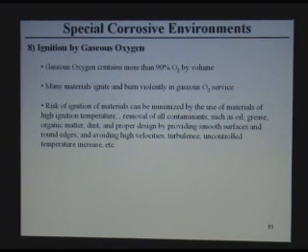Gaseous oxygen is a very dangerous material to handle, and it has ended up with a lot of accidents that killed and injured people. Gaseous oxygen is defined as having more than 90% oxygen in the gas. Once you have 90% oxygen, then you have to be careful of material selection for it, because oxygen in this concentration can burn metal like wood. It can burn steel, it can burn stainless steel, and it doesn't take long to burn these materials violently.